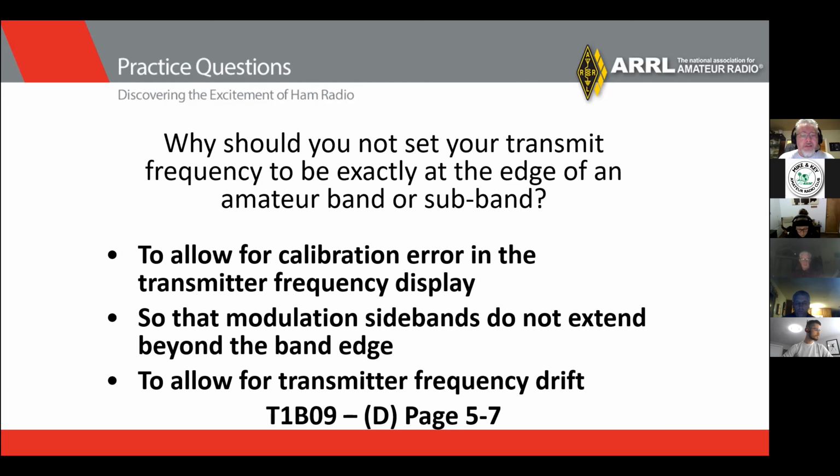Yes. Some of the modes, the dial frequency that you see on your dial is on the bottom end of your band, and sometimes it's on the top edge of your transmitted band, because you've got a range of frequencies you're actually transmitting in. So on lower sideband, your dial frequency is the top edge of it. So you're actually transmitting 3,000 cycles below up to your dial frequency. On upper sideband, you're reading the lower side of the band, so you're transmitting between that frequency and 3,000 cycles above that.